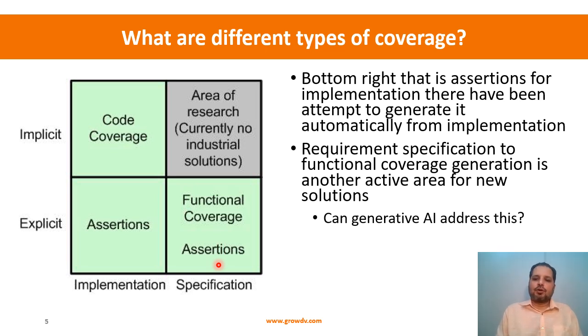For example, when you go to PCI Express 5, the digital core interacts through an interface called PIPE. Right now, for the PIPE interface I could do coverage using a combination of both functional coverage, cover groups, as well as assertions for the temporal relationships.